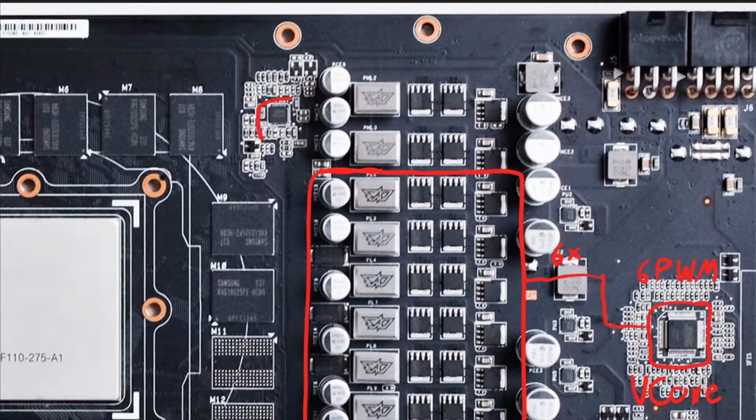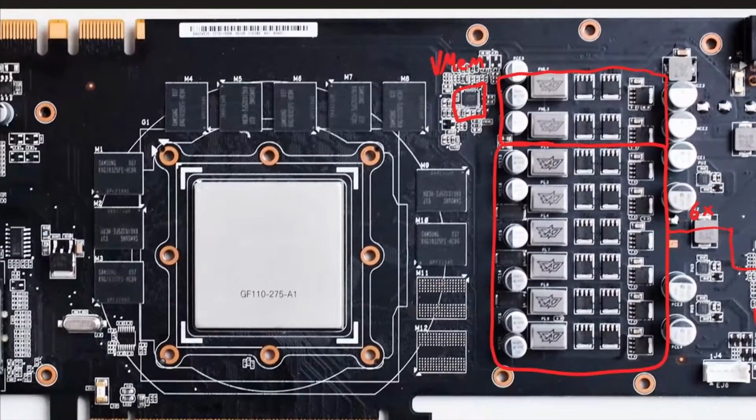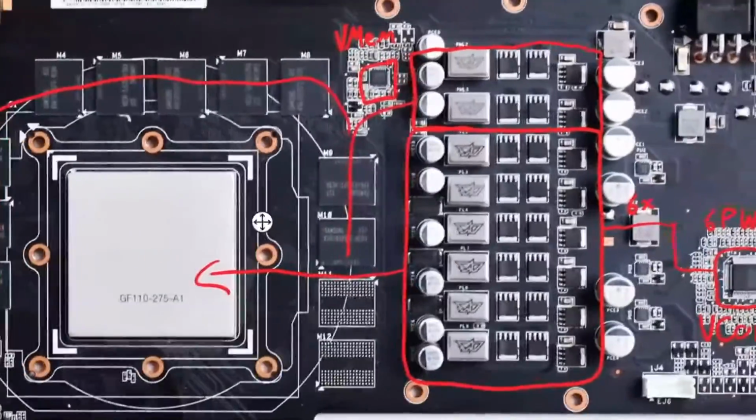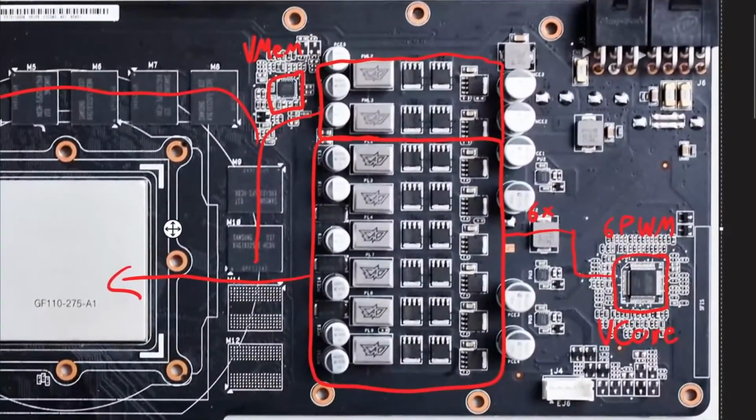Then you have this thing right here, the vMem PWM controller, and that one powers those 2 stages, which are the VRAM VRM. So the vCore powers the GPU, whereas this powers your VRAM. Originally I thought you only have one PWM controller, but as you can see here, there are 2 controllers for 2 different VRAMs.